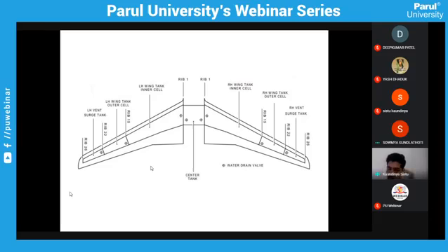Soumya, any questions regarding it? No, they have an idea regarding fuel dumping. Okay, that's good then. So they just open the left tank or right tank, whichever has more, as we are discussing, and they will dump it. But as you shared, if you have a difference of only a few hundred or mere thousands of liters, then yes, there is no need to consume more. What you do is pump both the engines from the single tank itself, instead of using both tanks. How you will do that, I will be discussing later on the slides.